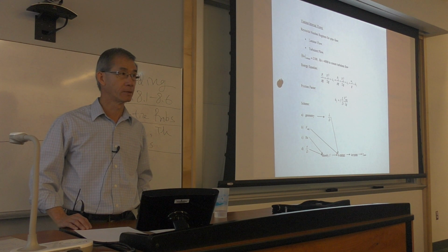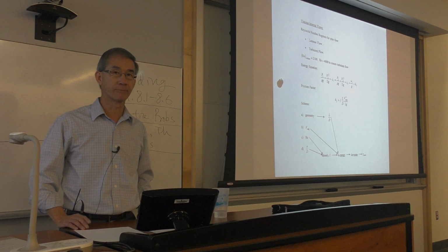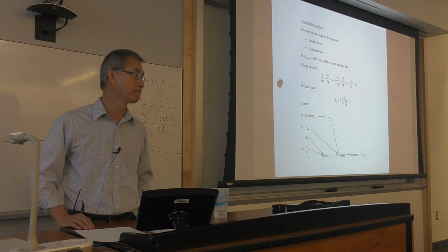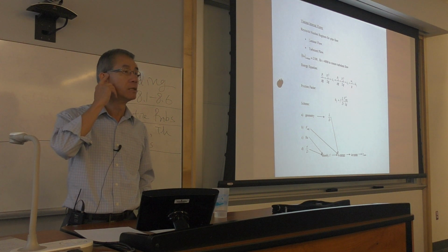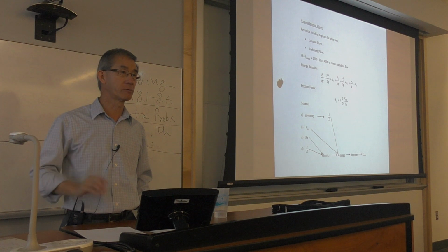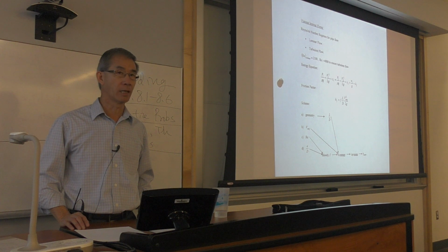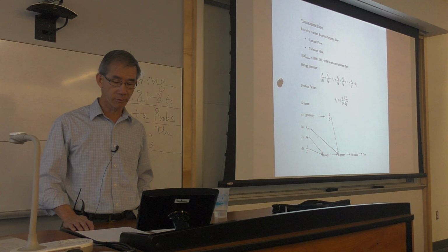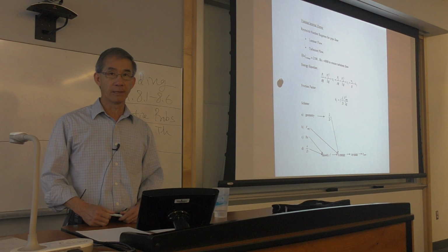In continuity, you will use the true area of the rectangular duct, which is the length times the width. Yes? When you say determining continuity, do you mean solving for volumetric flow rate? That's correct. Solving for the velocity in particular, because the problem gives you the volumetric flow rate, 20 cubic feet per minute, and then you have to calculate the velocity based on that. The area you use to calculate the velocity is the true area, not the hydraulic diameter. That's a very important detail that I mentioned at the end of the lecture last time, but it's very easy to forget.